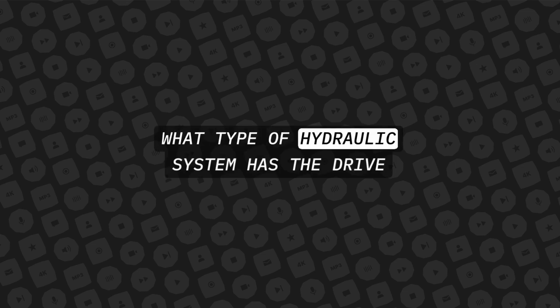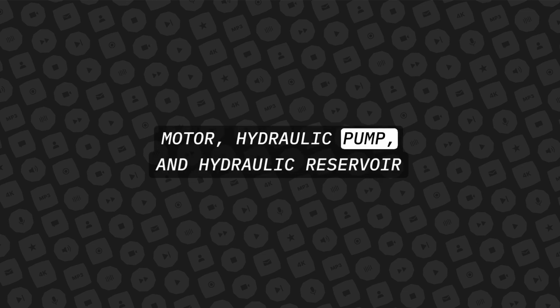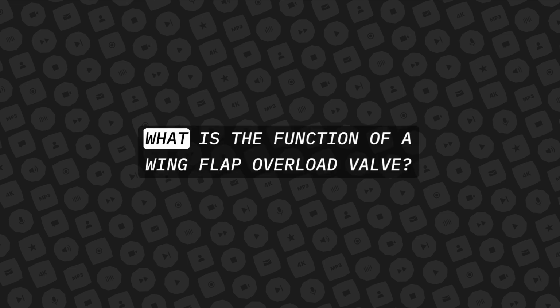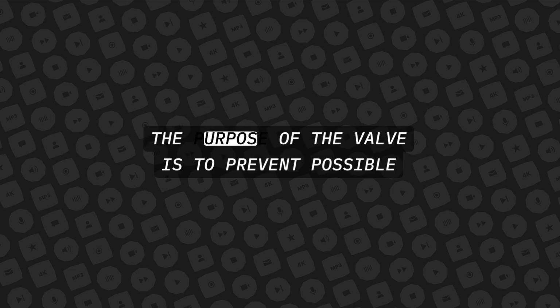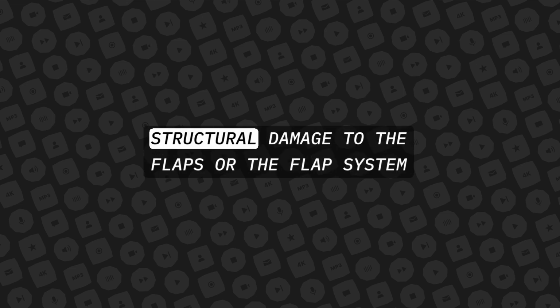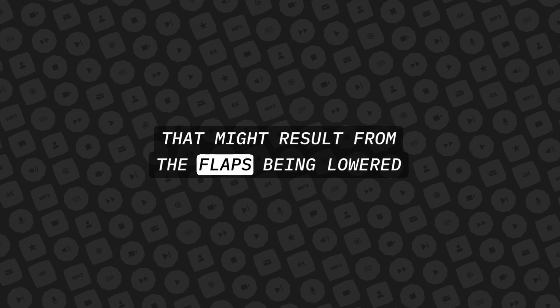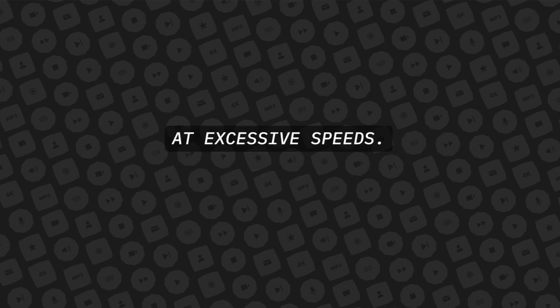What type of hydraulic system has the drive motor, hydraulic pump, and hydraulic reservoir all in one unit? Power pack. What is the function of a wing flap overload valve? The purpose of the valve is to prevent possible structural damage to the flaps or the flap system that might result from the flaps being lowered at excessive speeds.